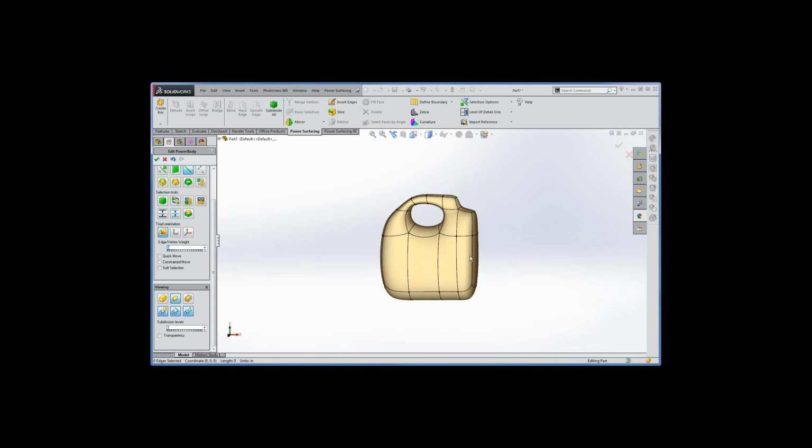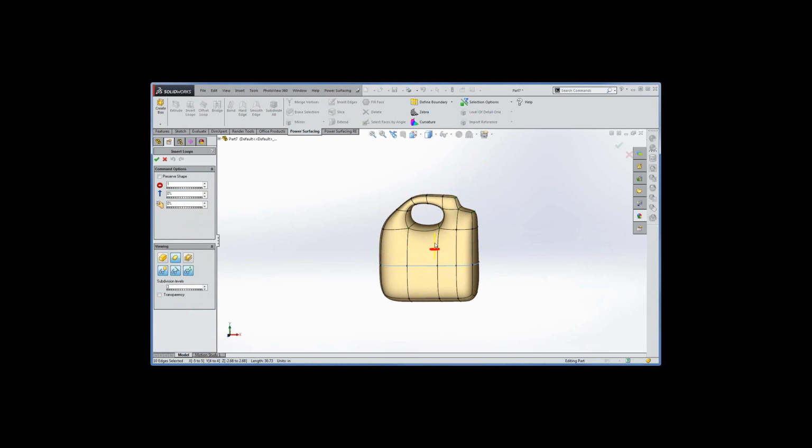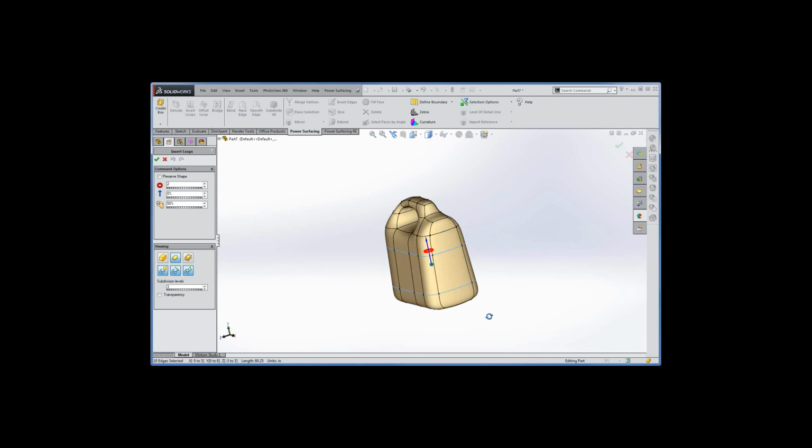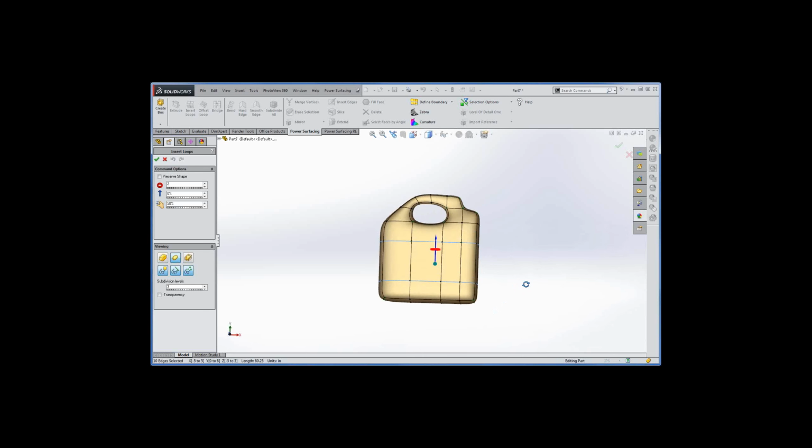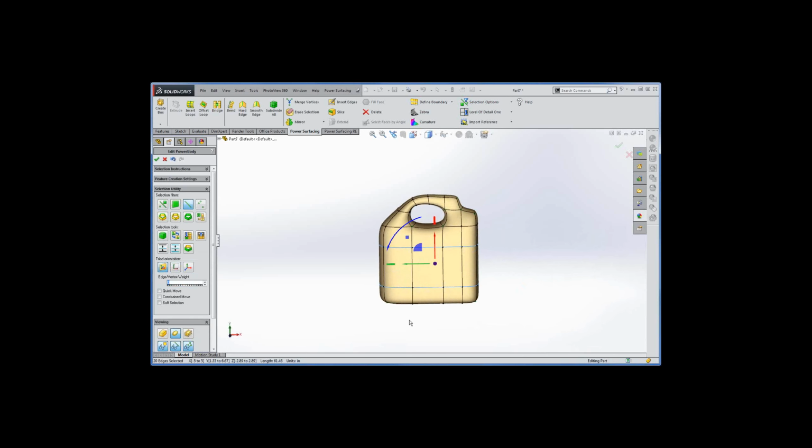So I'll go ahead and add another couple of loops, edge loops, once again with my right click. This time, I've got my 2 loops. We've got the option to pinch or slide the loops as well when we add them. And I'm going to go over here and I'm going to offset this to, say, 50. And as these loops get closer to the other edges, you can see we get more of a definition of our shape. So it's getting pretty good here. Right-click to accept this.